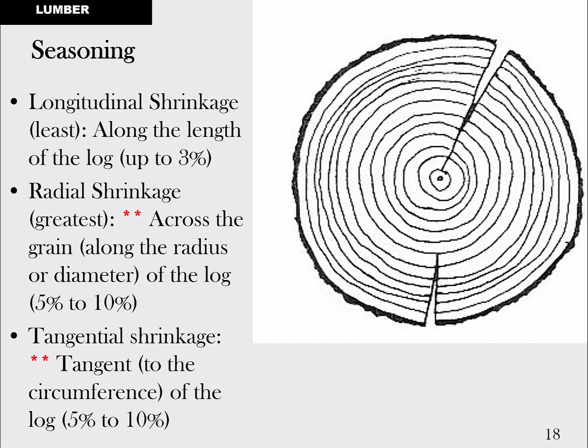They're both the same issue, basically. They're two different ways of looking at the same problem here. Because it's changing shape, it'll tend to crack along there, and it's maybe the bigger deal, because you're more likely to have cracks in the lumber from tangential shrinkage, that distortion that's going on. But it's around the same 5 to 10%, where softwood lumbers like pine tend to shrink about 10% tangentially. So we're talking about the circumference of this log changing, and it changes more along the outside circumference than it does in any of the inner circumferences when you're going around that log.